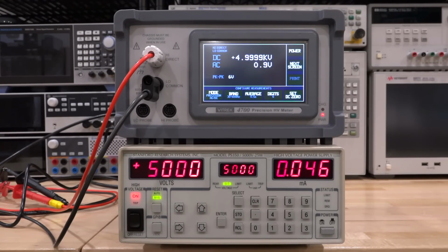Now, these kinds of power supplies do not work well at very, very small voltages because their output divider network is not adjustable. It's only a fixed division ratio. And at some point, you're just going to run into the noise. So, for example, if I set the output to 0, you can see that it will drop down, but it will never quite go to 0. It'll probably hover around 30 volts or so. As it's stabilized. Yeah, see, it doesn't really go below this. And if I turn it off, it does actually go to nothing because the DC-DC converter is turned off. If I turn it back on, then the lowest it can produce is about 30 volts.